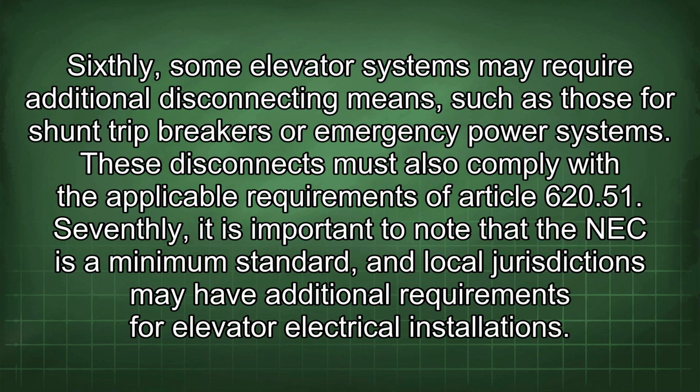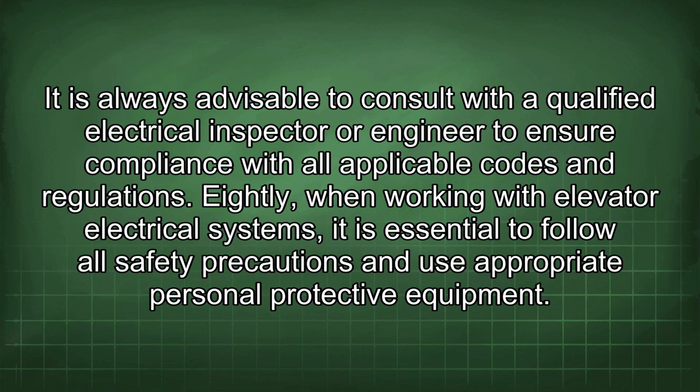Sixthly, some elevator systems may require additional disconnecting means, such as those for shunt trip breakers or emergency power systems. These disconnects must also comply with the applicable requirements of Article 620.51. Seventhly, it is important to note that the NEC is a minimum standard, and local jurisdictions may have additional requirements for elevator electrical installations. It is always advisable to consult with a qualified electrical inspector or engineer to ensure compliance with all applicable codes and regulations.